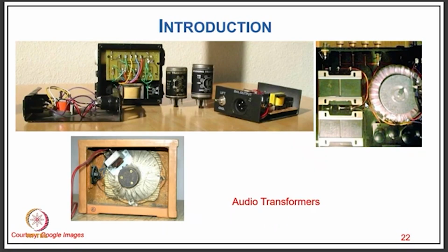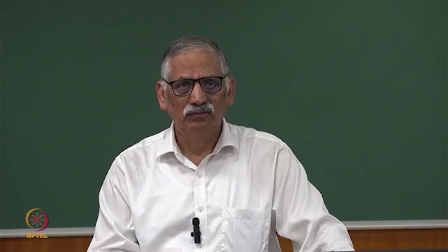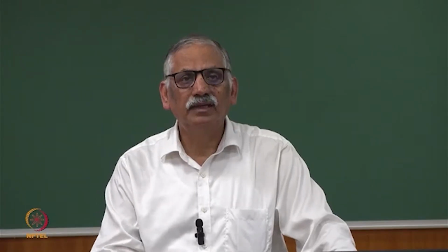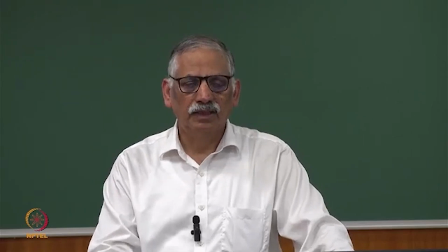Then you have different audio transformers which are used typically in electronics, in all the amplifiers, sound amplifiers, where you use a transformer which is normally used for audio frequency. This is an interesting application, which you call impedance transfer using transformers. What we do here: we might have probably a mic or speaker of around 10 watts, having hardly about 3 ohms, 5 to 10 ohms, which gets reflected as 5 to 10 kilo ohms on the amplifier. So that the amplifier is not loaded.